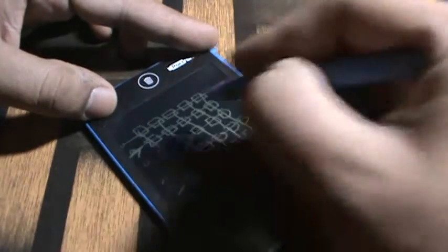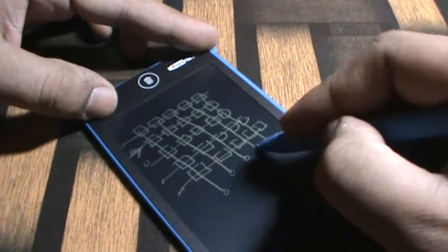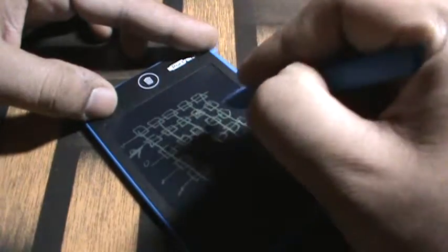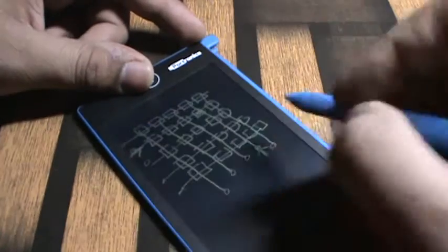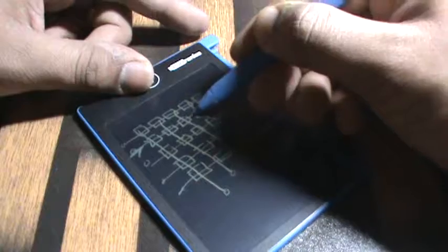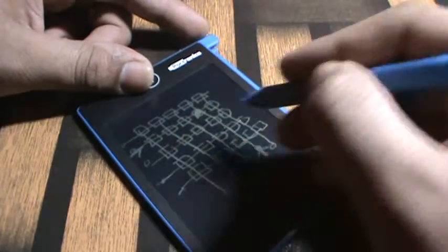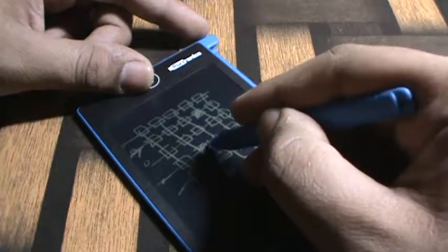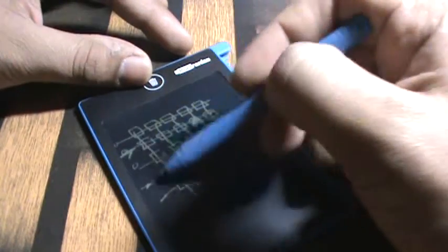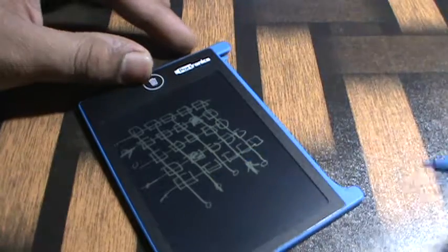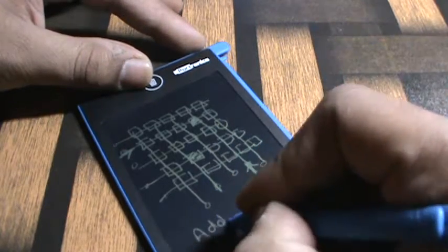So when we set some value to this input, and the same value we set over here, then that corresponding cell actually stores that value, and that's what RAM does. So this cell and this cell are going to affect this particular unit. Similarly, this cell is going to affect this particular unit, and we can store our 8-bit number into our RAM in this way. But who is going to decide which cell to select, which particular row and which particular column to select? That is known as address.